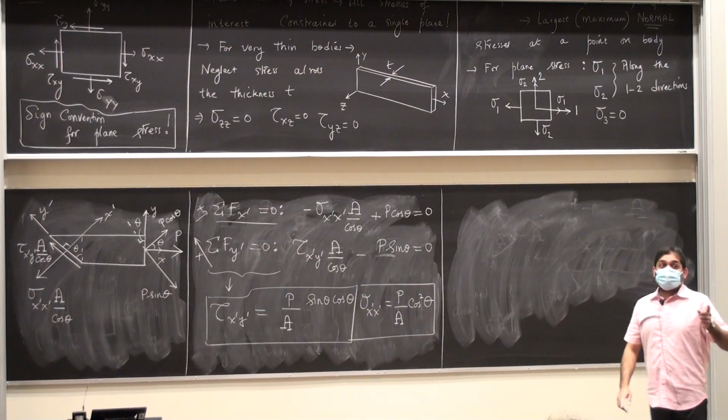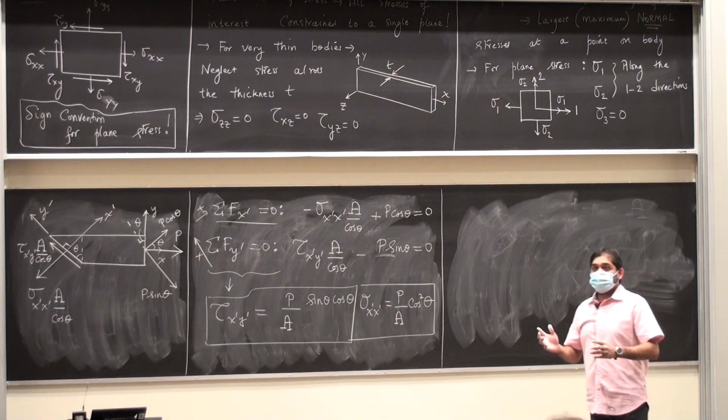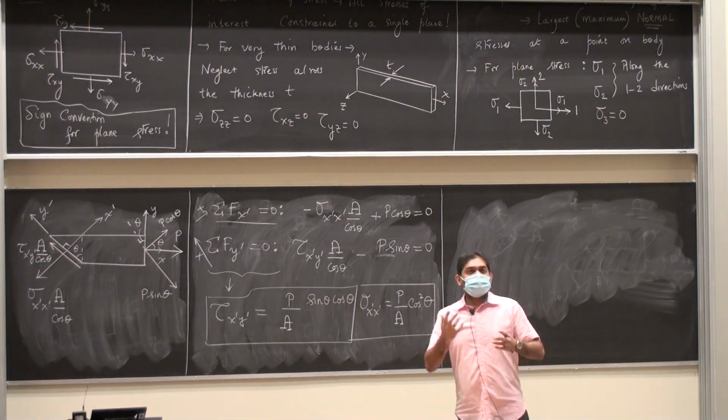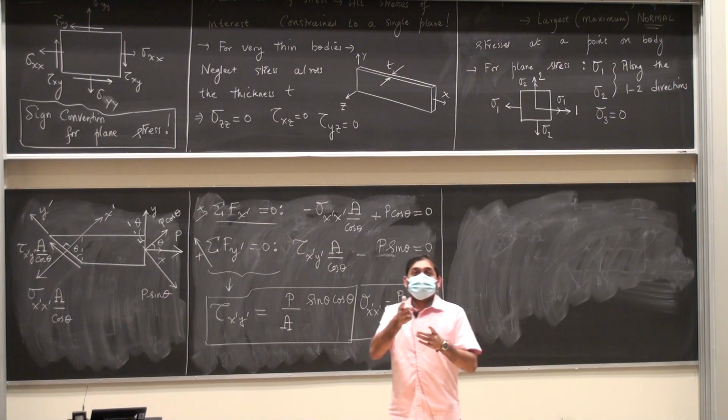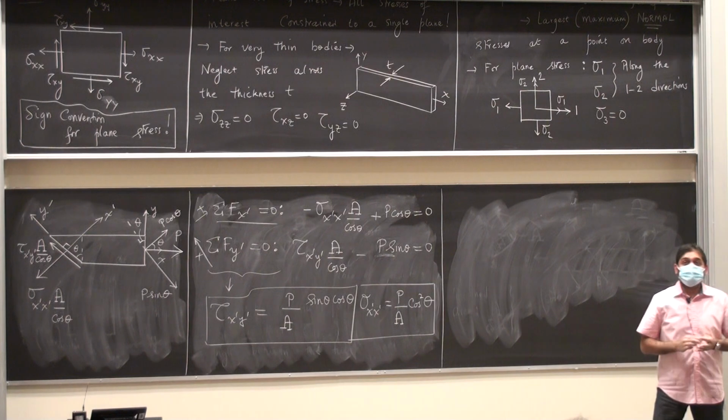What do we know about ductile materials? What I just told you, right? The failure is caused when the shear stresses are a maximum. What am I seeking? I am seeking the value of that shear stress, and I am also seeking at what plane, that is at what angle to the loading plane, this is going to happen.